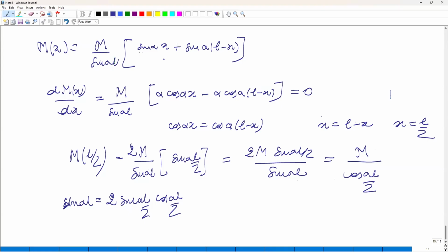Actually, we have analyzed two structures. One was the simply supported with one moment. The other one is simply supported with two moments. They are two different structures. The structure is the same, but the loading conditions are different. The buckling load has not changed. The buckling load does not depend on the external forces, on the external actions. The buckling load only depends on the boundary conditions. So it's not that if your structure is more loaded than another one, its buckling load will change. The buckling load is always the same, and it only depends on the boundary conditions.